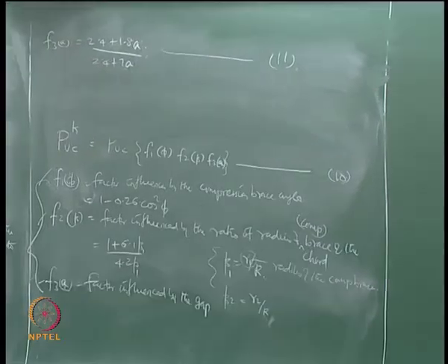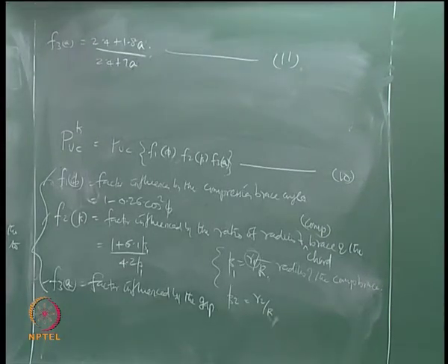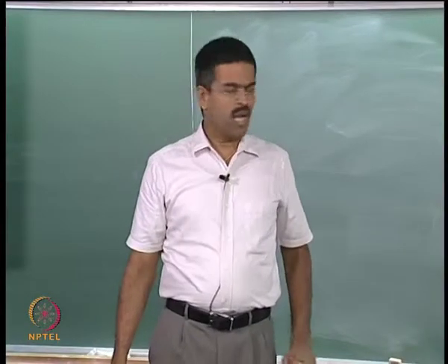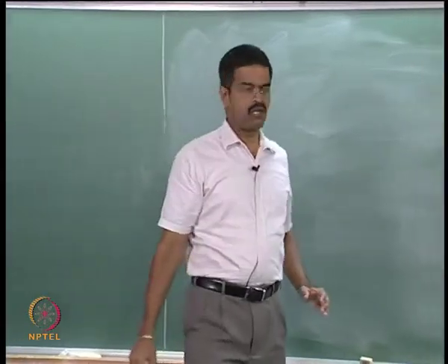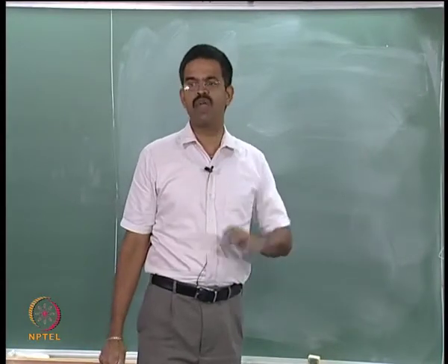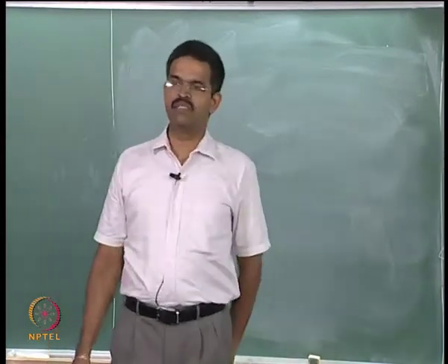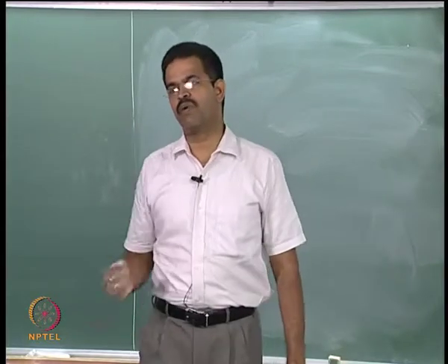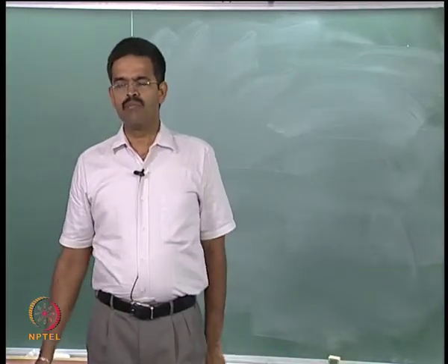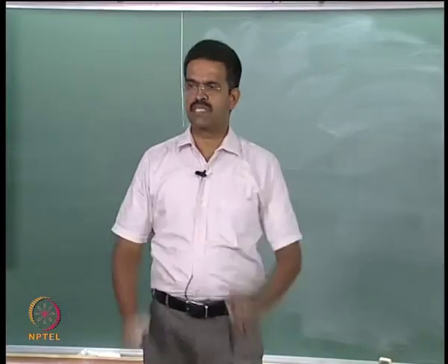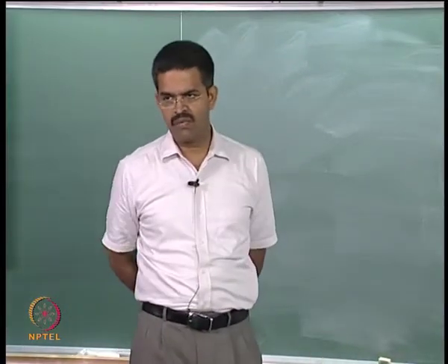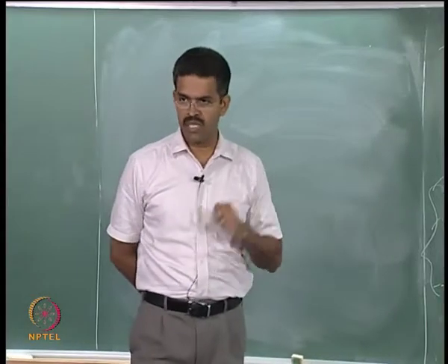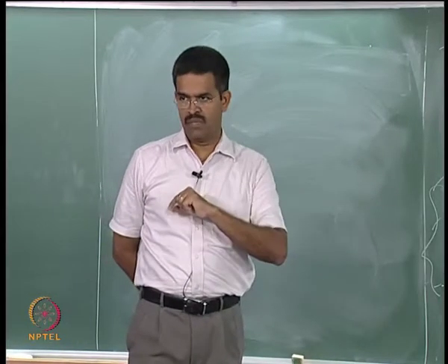So in this lecture we discussed the ultimate strength capacities of various joints. We understood that the compression brace is governing the design. Why are we not looking for an analytical model or analytical behavior of these kinds of joints? Because the failure is a combination of plastic yield as well as stability problems under compression. The moment you have a stability problem, you have got PM interaction. We already saw in the last lectures that whenever you have a combination of loads, then the effect of one on the other is influencing.